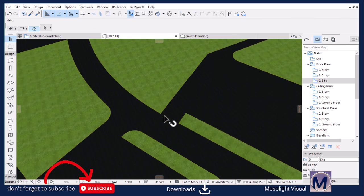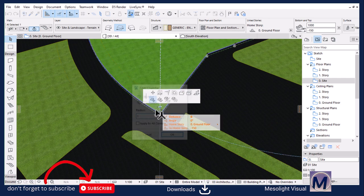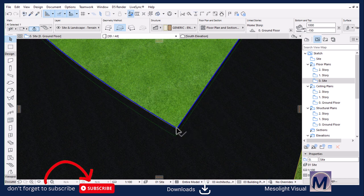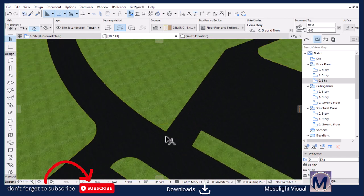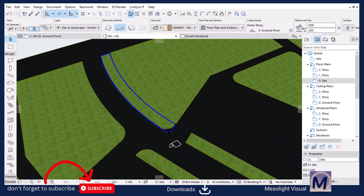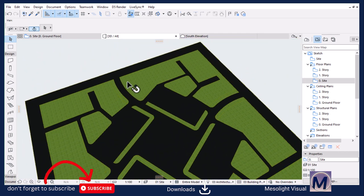What we need to do is fillet this point. Oh, it's because there are 2 points there. Take this point to the corner and then pick that one and fillet by 3.5. Oh, there are 2. Okay, let's do the same to this one. I don't know why they're on top of each other. I can get rid of one. No, but yes, I can get rid of one.